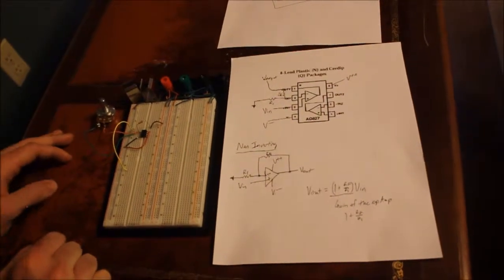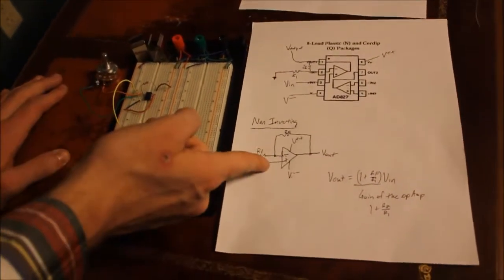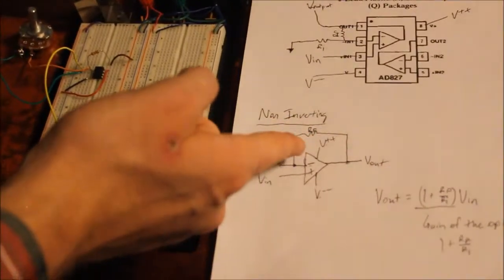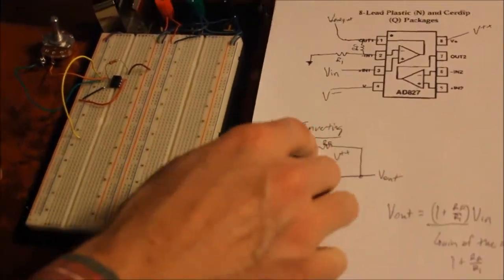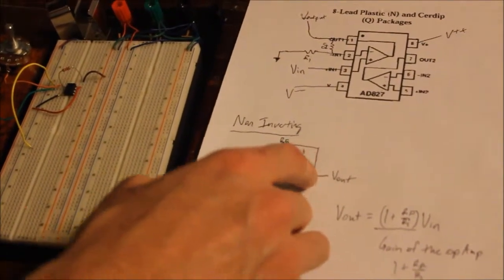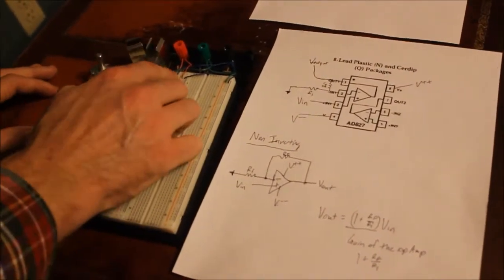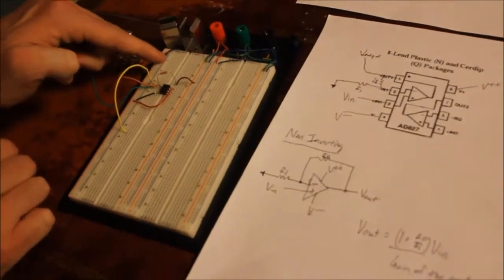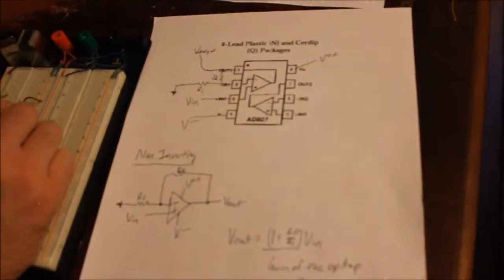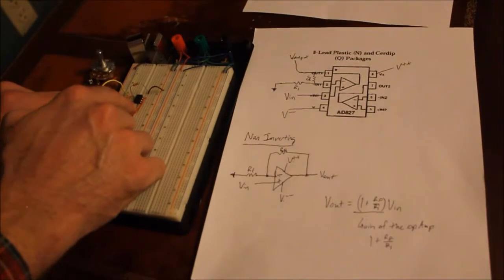All right. As we've previously described, to make this audio amplifier, we're having a non-inverting op amp with a potentiometer here as the resistor in parallel with the inverting input and the output. So what we've done here is shown you how to work with this chip on a breadboard, treating this green line as ground, the red line as positive, and the blue line as negative. Here we've connected from positive to this V plus up here, the top right pin. The negative we've connected to the bottom left pin, V minus.